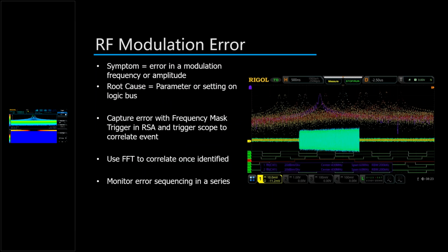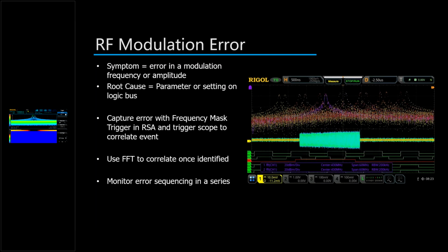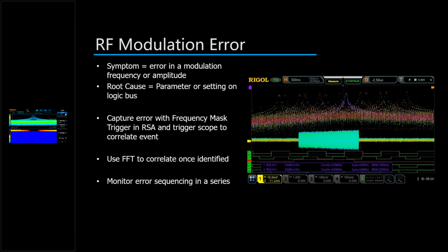And then the last interesting way to look at this on the oscilloscope is with this kind of a signal here. If we wanted to do a long-term analysis of all those pulses, and either set up a mask or record them and see them over frequency, we can use a combination of the multiple FFT capability on the scope.